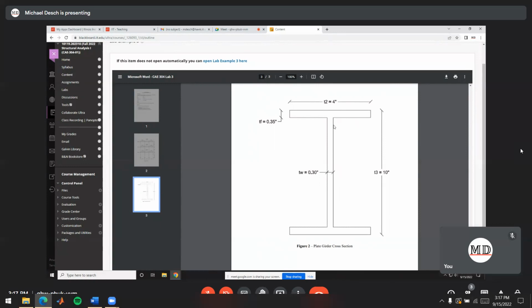There's a couple situations where we might need to go and create a custom built up section like this if we're doing some really custom situation, or if we need like really, really deep beams that are way deeper than like the standard beams go. Like big plate girders on bridges come to mind. Sometimes those can be 10, 15, 20 feet deep, very large. And regular rolled sections only go up to 44 inches deep.